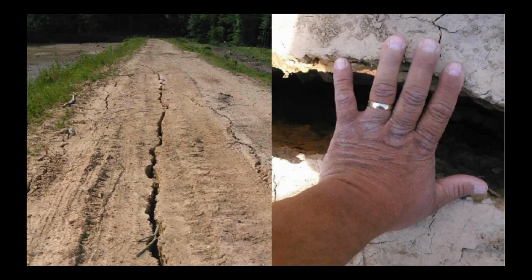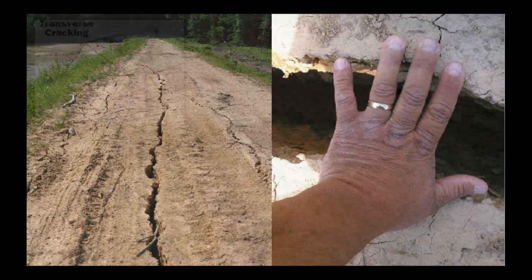Now, why would you get a crack like this in a dam? It could be for a couple of reasons. This particular crack was related to a sudden drawdown, so that the reservoir was up high for a number of days. It saturated the upstream slope, and then it was drained very quickly, so that the embankment didn't have a chance to drain. It was saturated, and that additional water load caused it to crack.